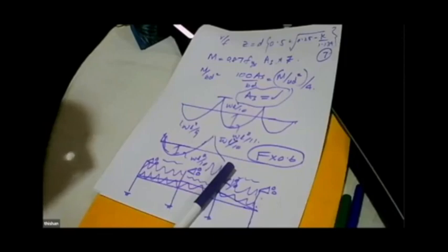In design, there are 2 levels. The first level is preliminary design, where wealth of experience should come in. At that level, BIM can't do anything. But once you design and start producing the drawings, BIM can do a lot of things by coordinating among all the people who are involved in the project.